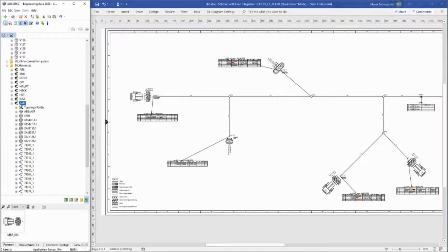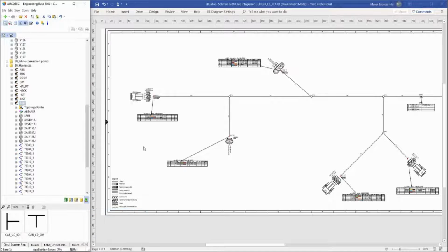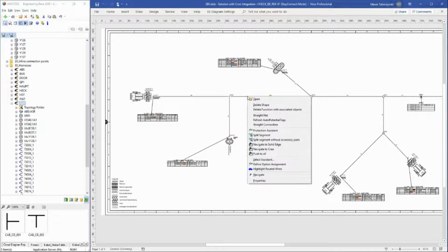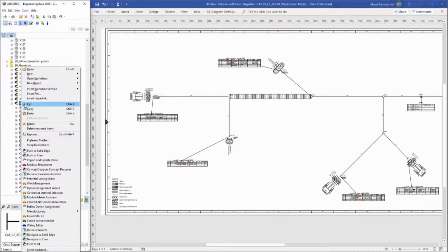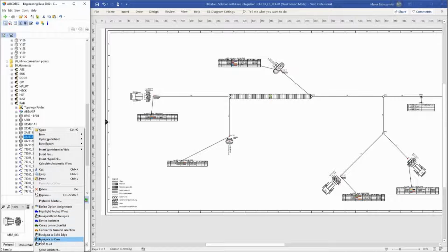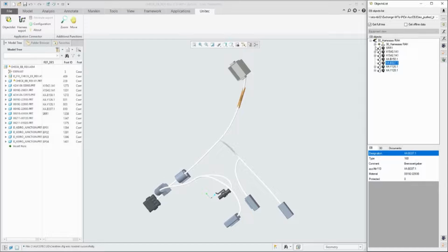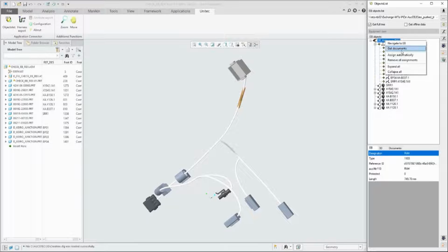You have the view with the flattened, what we call topology, and we have as well the information about the wires which are connected between the connectors, and we see all the length information coming from the 3D system. Now we can additionally define protective material for the bundles, and therefore we have a diameter we have to fulfill, and we can check in the 3D world if there is any mechanical collision, and this will be displayed also in an automated way.